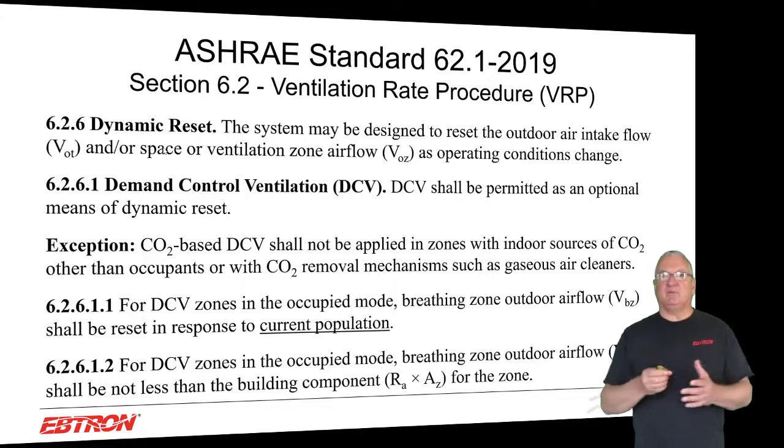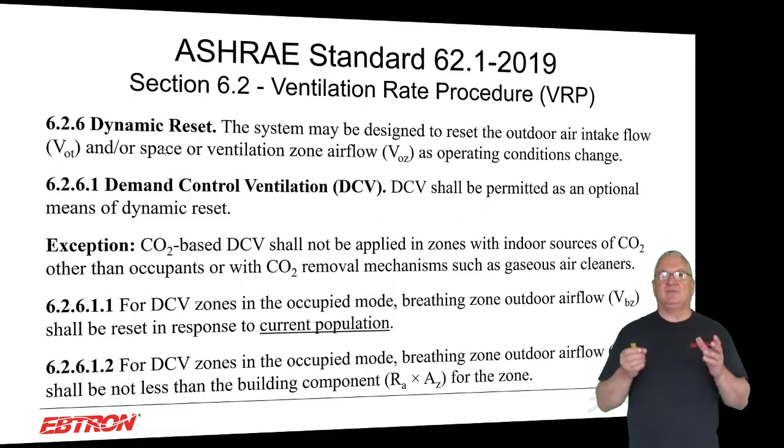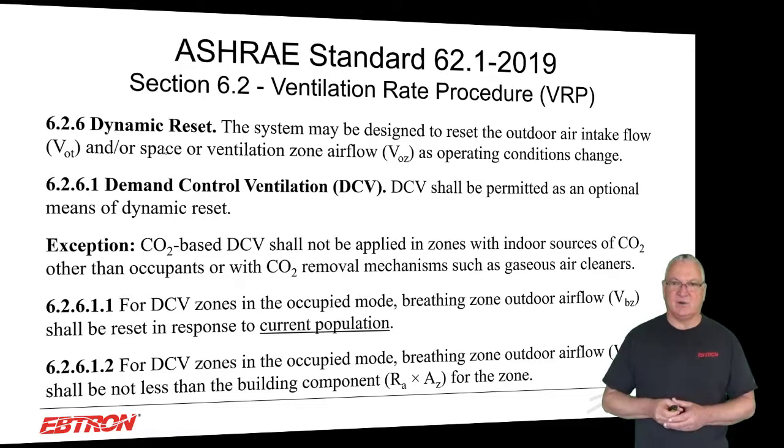But yet I have people all over the place doing things with the IAQ procedure and reducing ventilation rates with filtration and air cleaning and then still doing CO2 DCV. There's just way too much misunderstanding out there. So hopefully this helps you out.